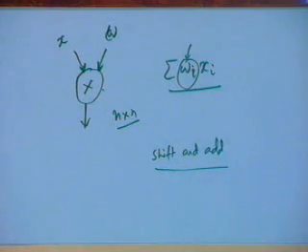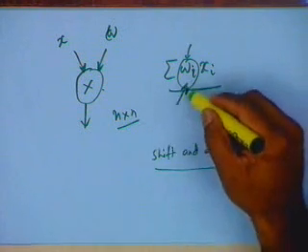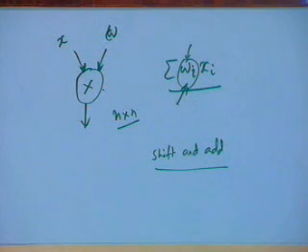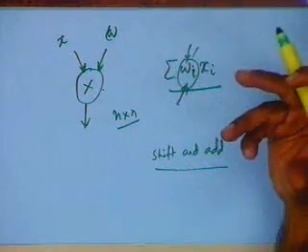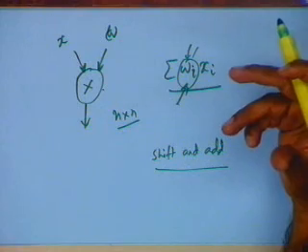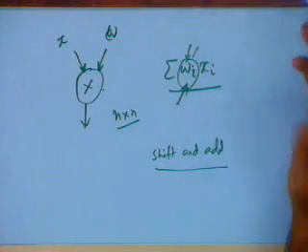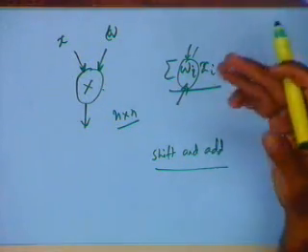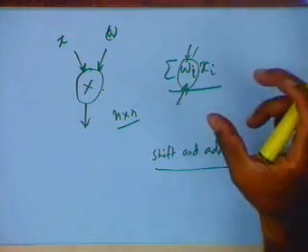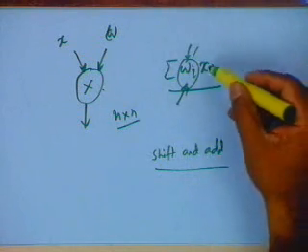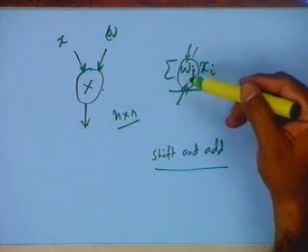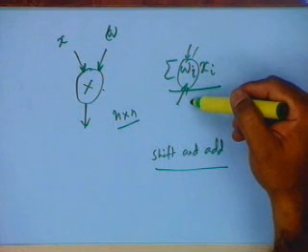I don't have to have a shift and add stage for each one of them, because I know this wi, I know the number of ones that are going to be present, so I need to perform addition only for those. And here there are very interesting ways of coding these weights so that you actually reduce the number of ones. A string of ones can be replaced by one addition and one subtraction, and so on.